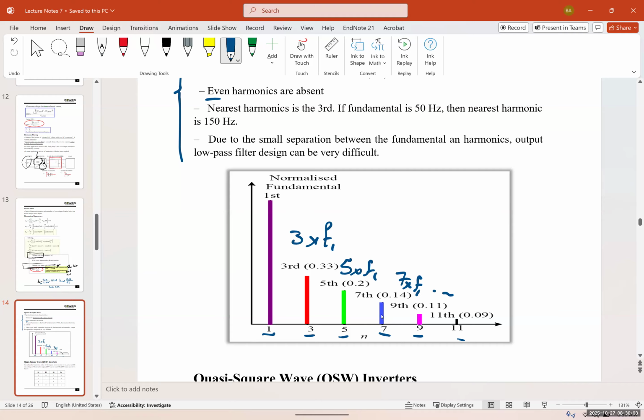and so on. So you can see that the higher the harmonics go, the effects become less and less. Usually the rest has minimal effect. It's negligible, okay? 9th or 11th, depending on how good you want your output signal to be. If you want to be very pure and accurate, for a medical device, you use up to the 11th harmonic. But the good thing is, when we filter after the third harmonic, for example, all of these are going to be eliminated, okay?